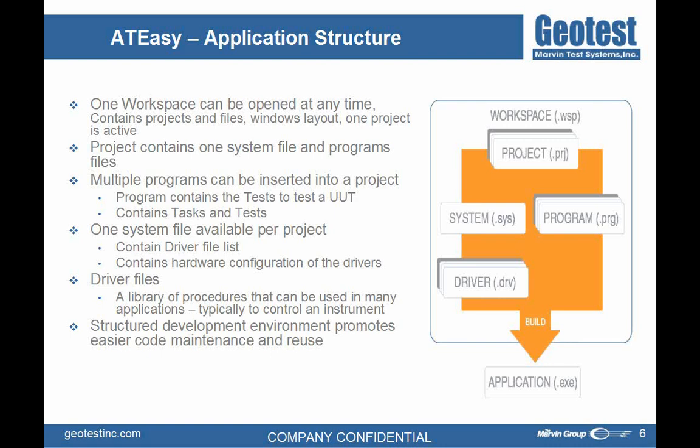Within a project you have three modules. There are the system module, the program module, and the driver module. And these modules are placeholders for the code for performing specific functions within your ATE application. For example, the system module is where you would place code and resources that are used for configuring and controlling your system apart from running tests and making measurements. So anything having to do with, for example, initializing the system, setting up default conditions, a termination process, the code to perform all of those functions would be placed in your system module.